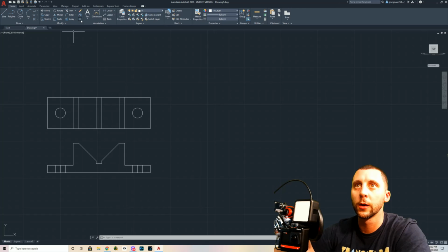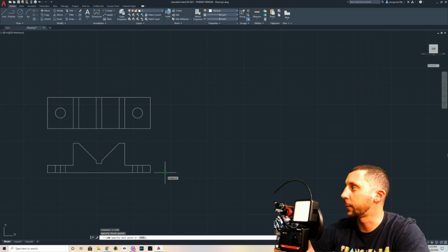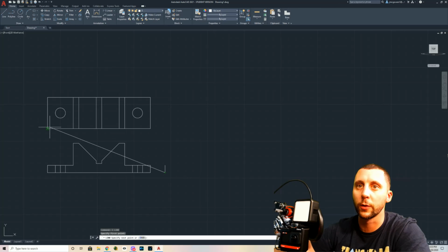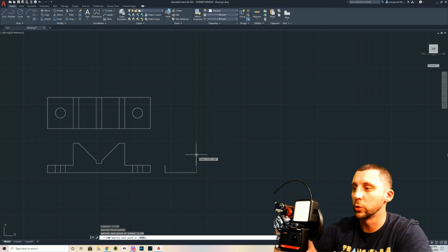So right view, okay? Offset 1 inch. We're going to go off of this, and that's going to give us a position of the bottom left corner. The depth of the drawing, like we said before, from here to here is 2.125, which is 2 1/8. And then it goes up to total. It goes back 2.125, and then it closes.